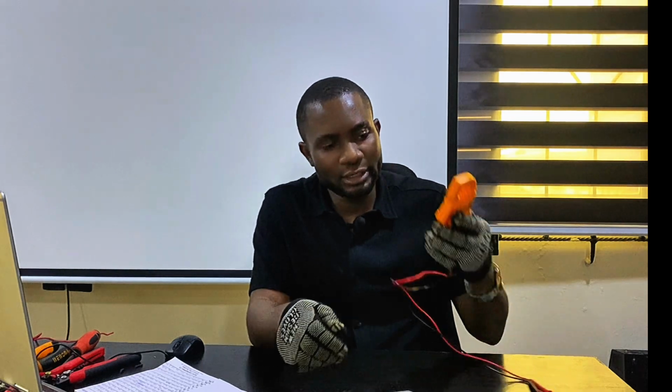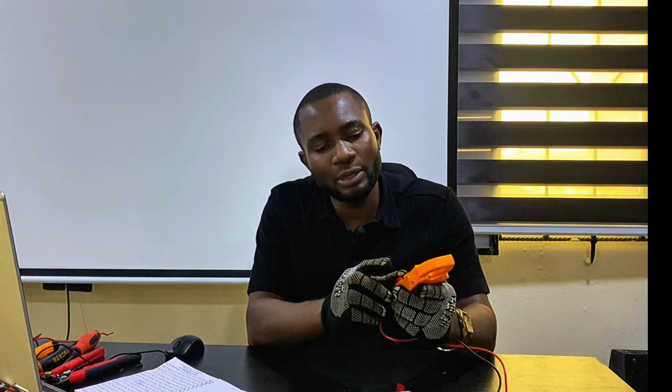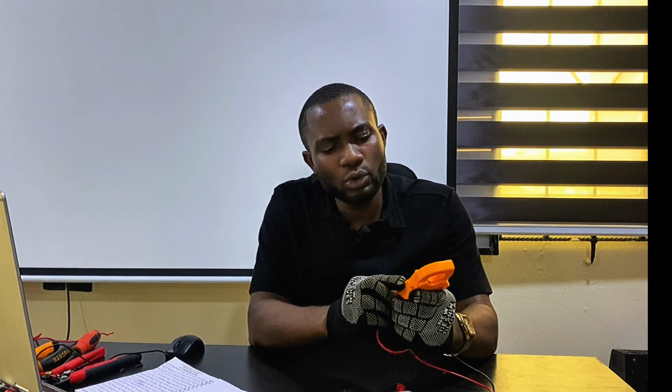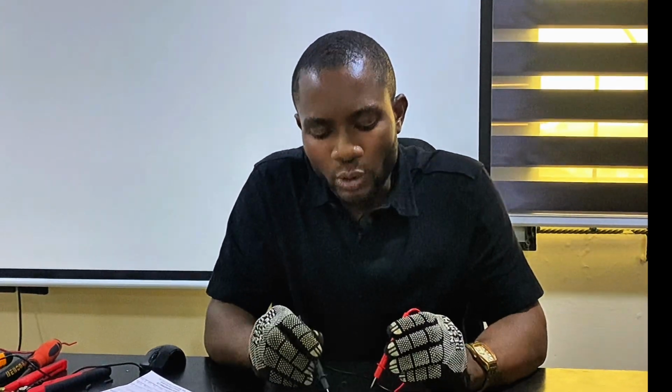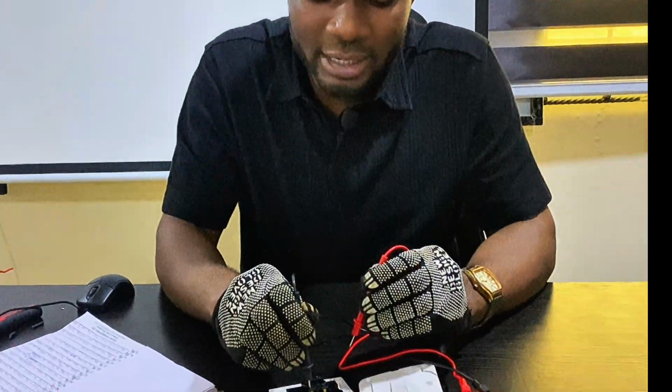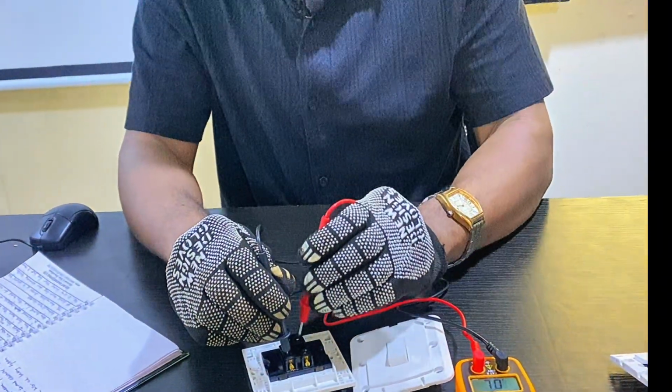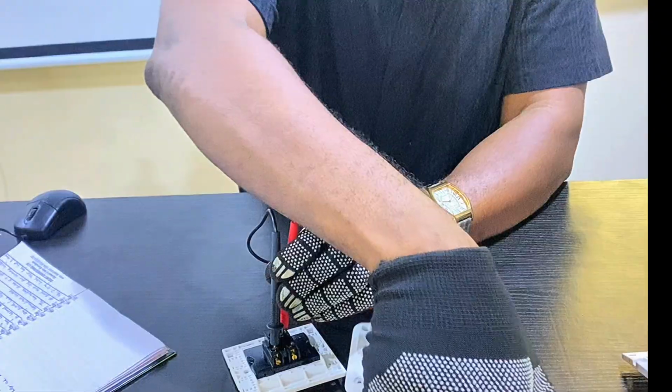On this circuit diagram, you would see that terminal 1 is looped to terminal 4, and terminal 2 is looped to terminal 3. So in that case, if you do a continuity test now, this is a clamp meter, but it has a multimeter function. If you take this to your multimeter function and test the continuity, this is terminal 3 and this is terminal 4. Then this is terminal 3 and this is terminal 2. When you come closer, you will see that there's continuity.